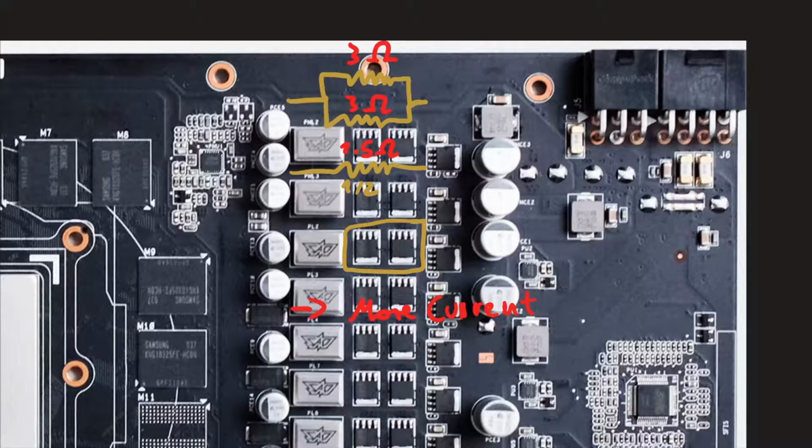So if you put two of those in parallel, you can handle double the current. Like if you have two 30 amp low side MOSFETs and put them in parallel, you can handle 60 amps per phase now. And the other thing that I've already talked about is half of the resistance. So it lowers the resistance for the low side.